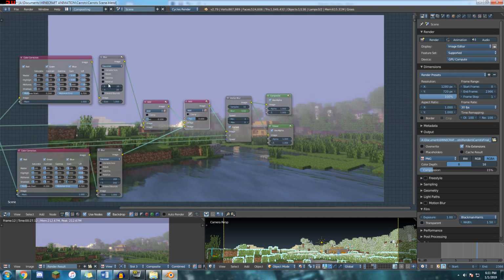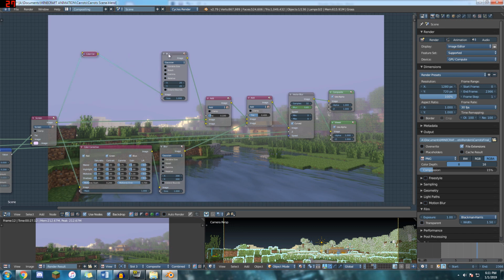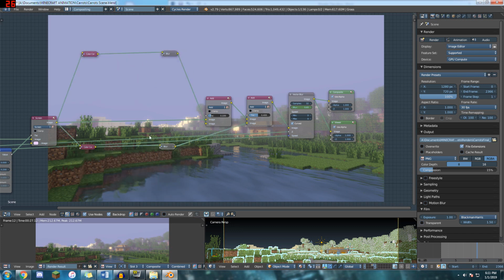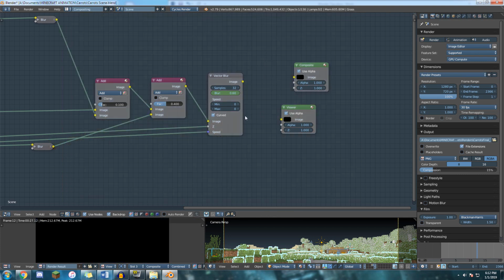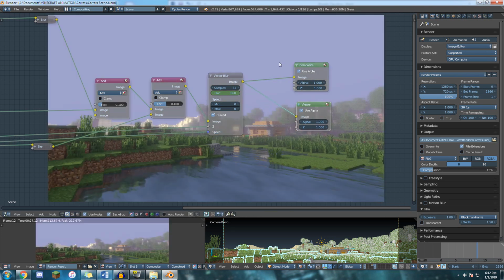And if you use H, you can hide them, which just kind of minimizes things. Doesn't really get rid of it. It just makes it a little easier to see. You can hold Control and left click to drag and cut if you want to cut across some different cables all at once. Really good for mass cutting a whole bunch of stuff off. Or if you hold down Shift and left click and drag, it will connect the cables together into a reroute, which is nice if you want to just have one thing reroute at the end.